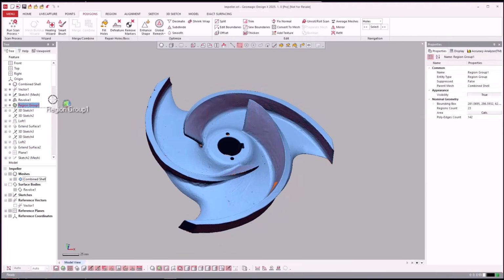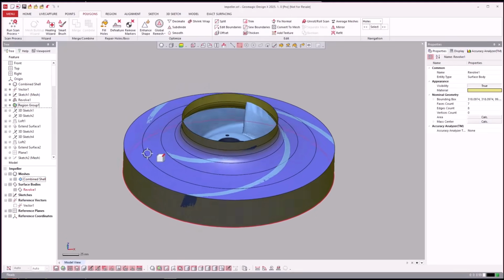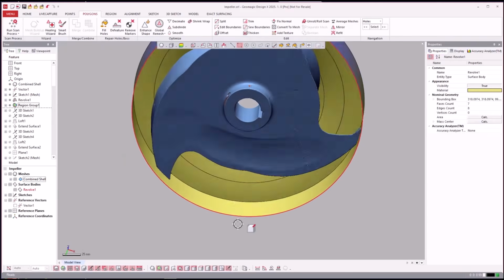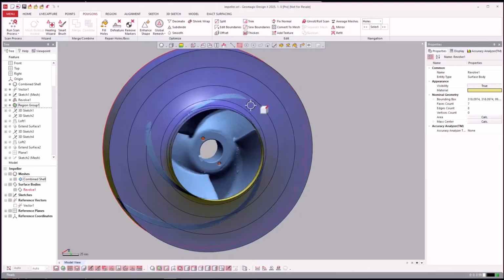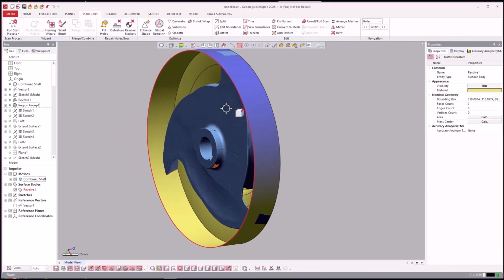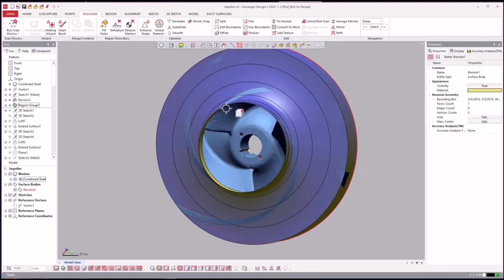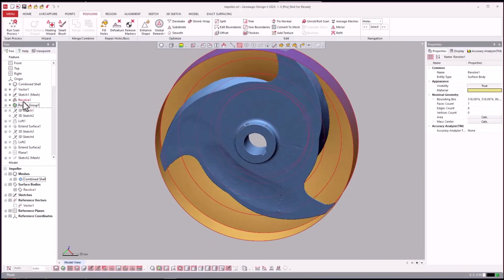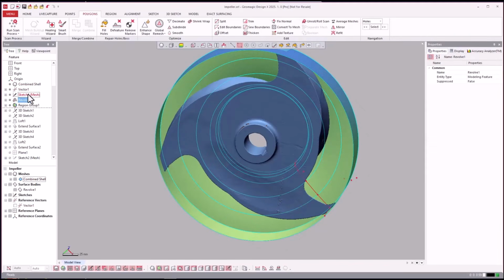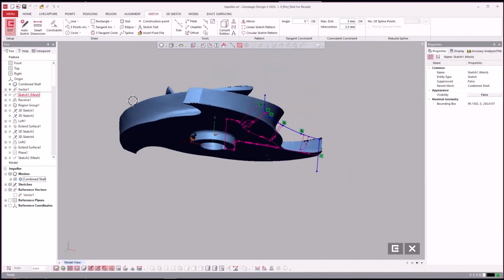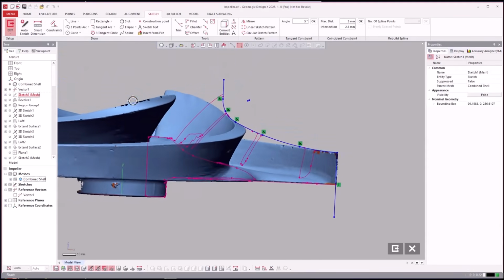And we revolved the external shape here. So we'll turn on the surfaces. We went ahead and did a revolve of the outer trim line of the entire part. This is kind of like modeling the housing that this is going to go in right out of the get-go, right? So go ahead and model that, and you can see, let's just edit that sketch. See what we did there. I think that shows it better.